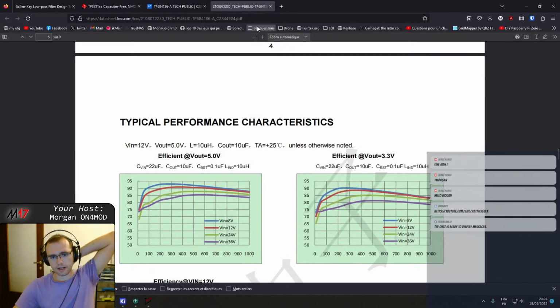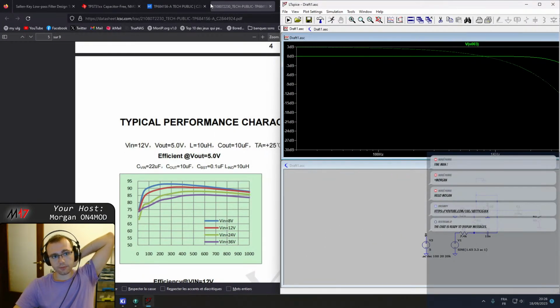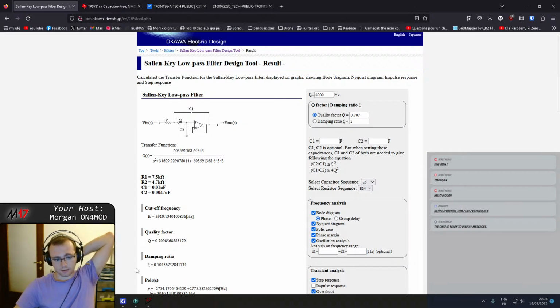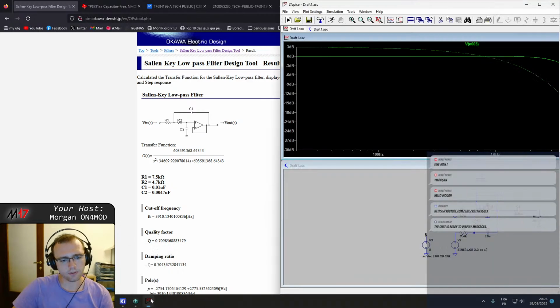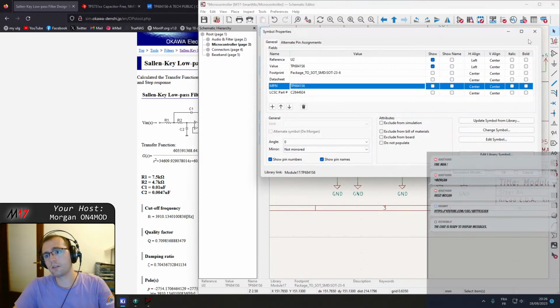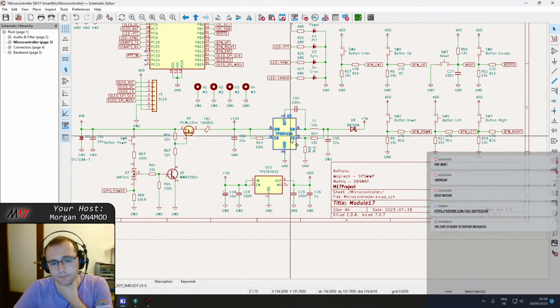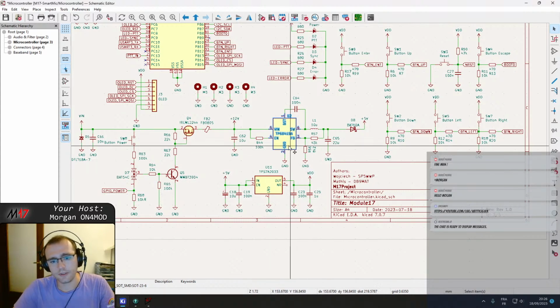Anyway, I don't really like powering such an amp directly from a DC-DC converted supply. So I would prefer to use the 3-volt supply, which is VDD.